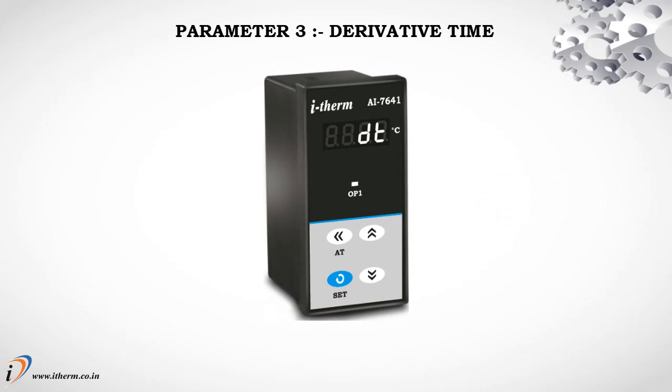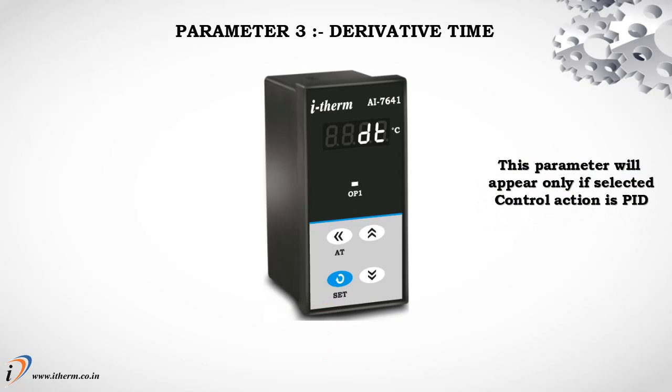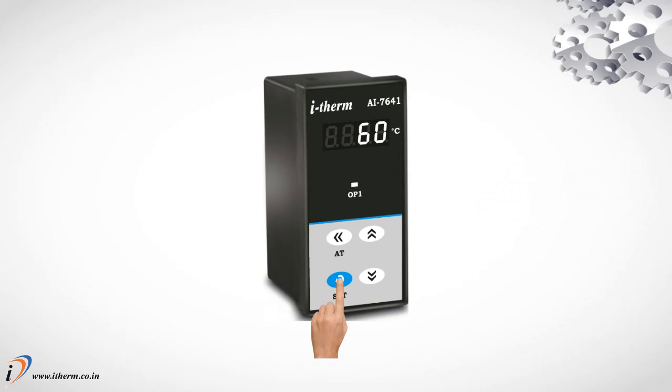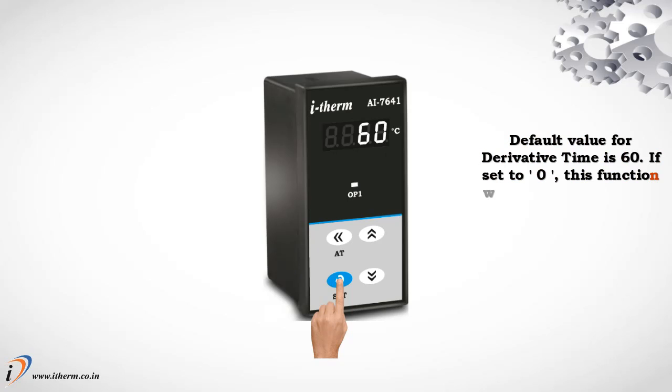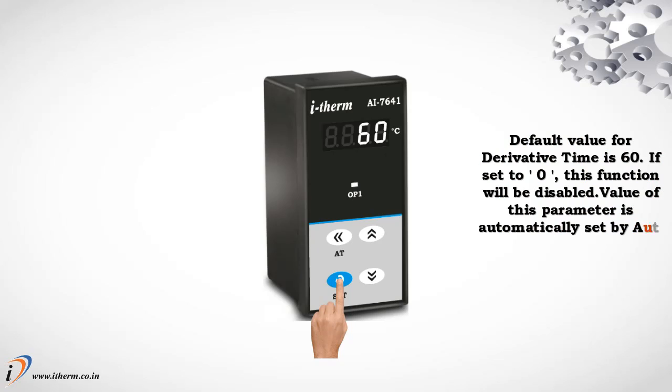Parameter 3, derivative time. This parameter will appear only if the selected control action is PID. Default value for derivative time is 60. If set to 0, this function will be disabled. The value of this parameter is automatically set by the auto-tune function.